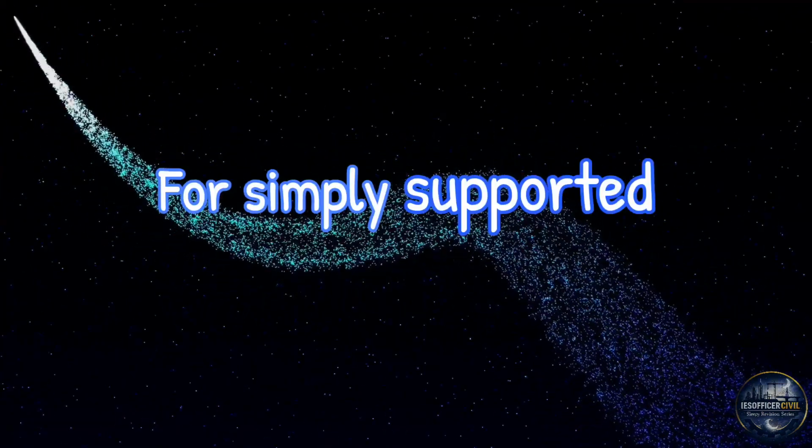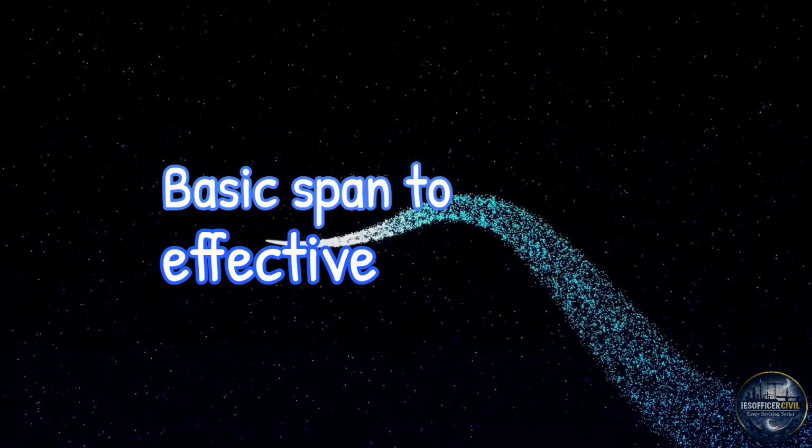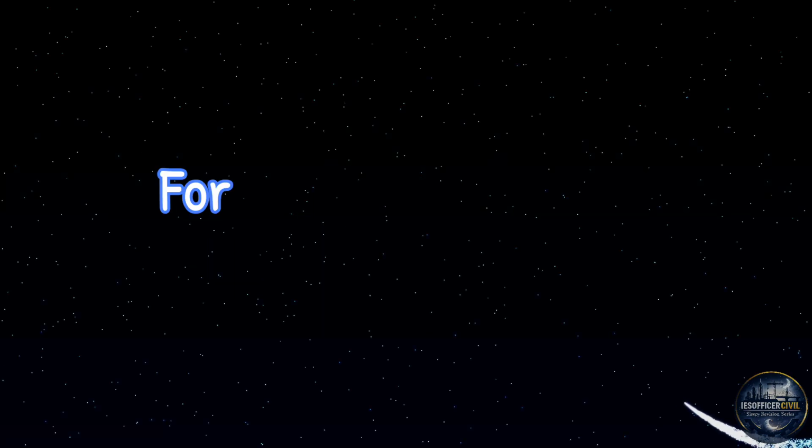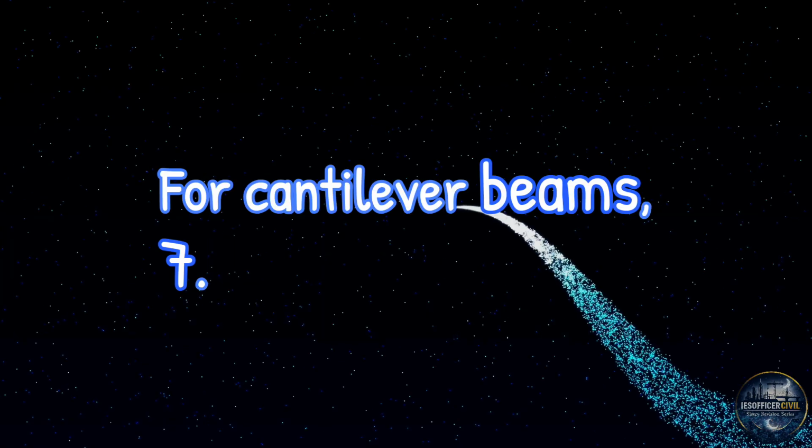For simply supported beams, basic span to effective depth ratio is 20. For continuous beams, 26. For cantilever beams, 7.